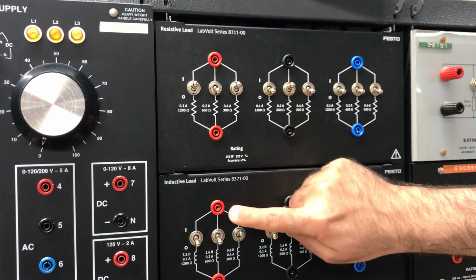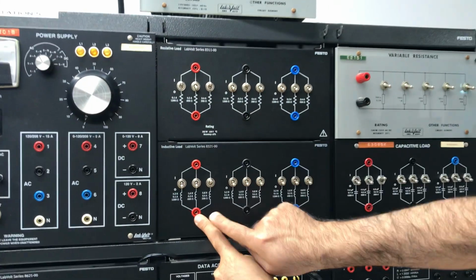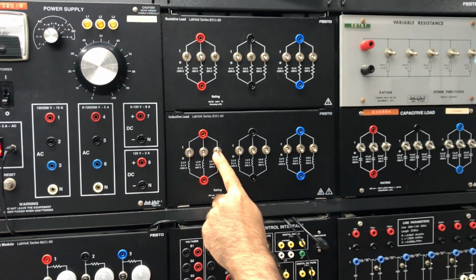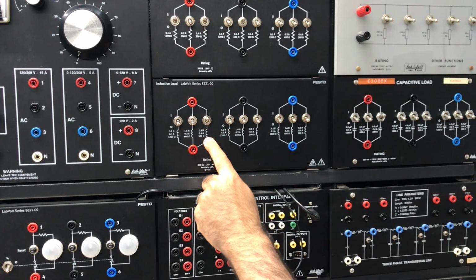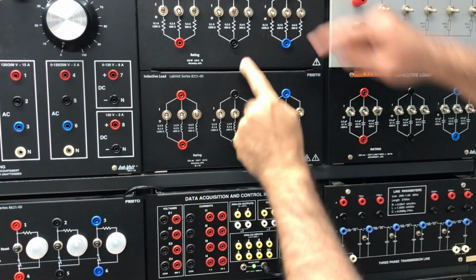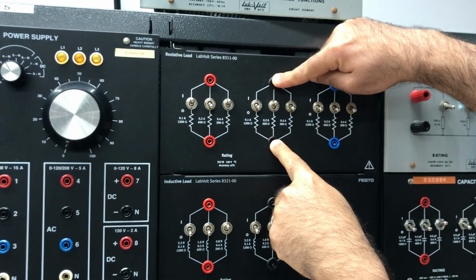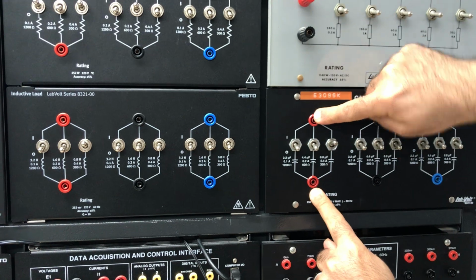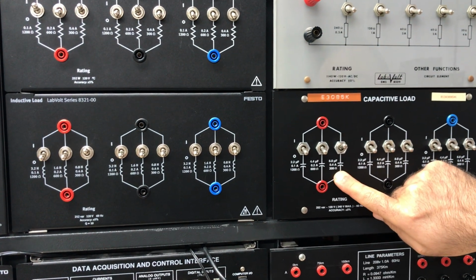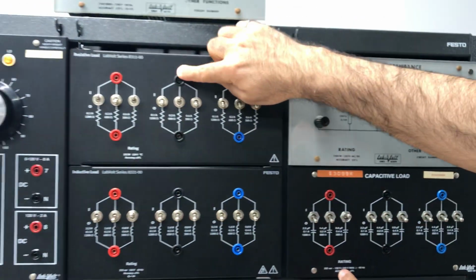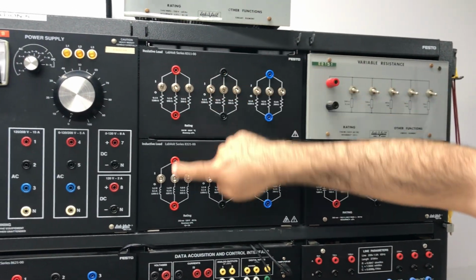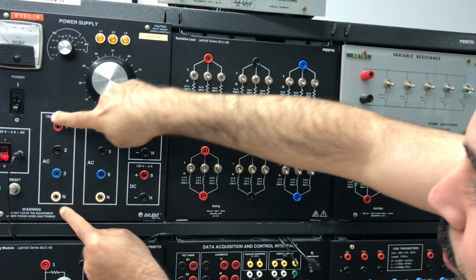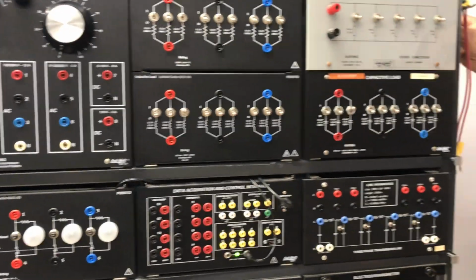And this branch is going to be connected in series with this branch that has only 300, so I'm going to open these two, and this one is on, so I have only 300 ohm reactance. Again, I'm going to connect this one, which is 600 ohm resistor, in series with this one, which is capacitive load that has 300 ohms. So this branch will be connected in parallel with this branch, and those two are going to be connected to the power supply. This is what I'm going to do right now.